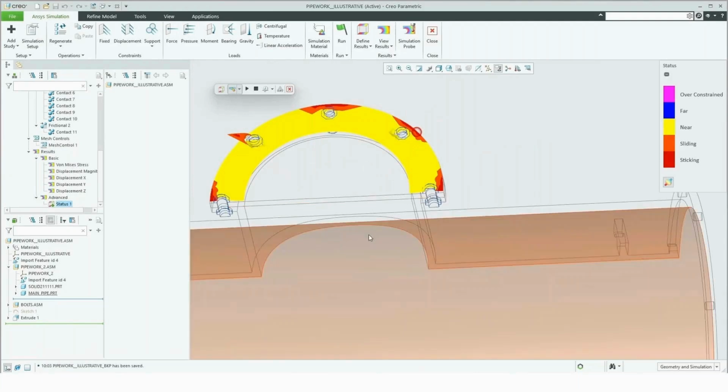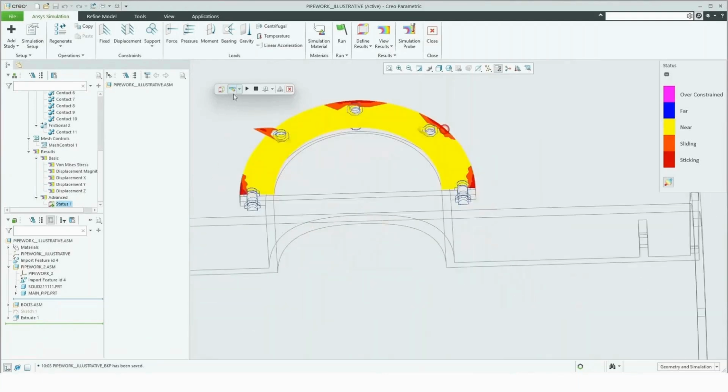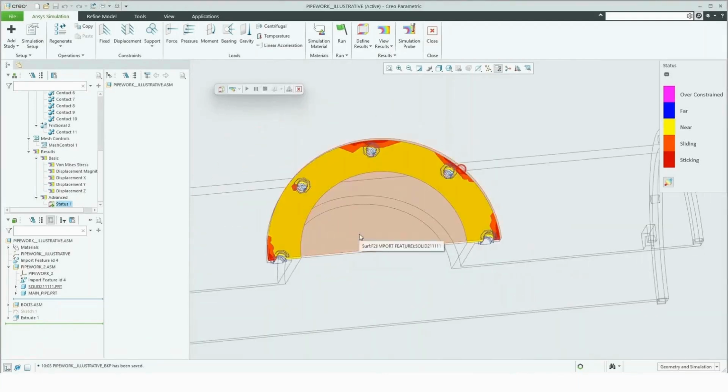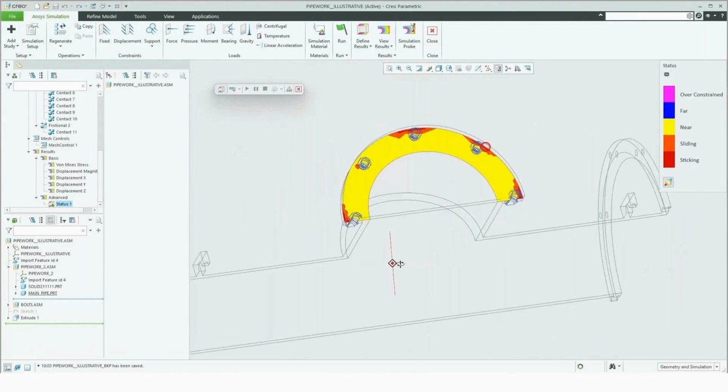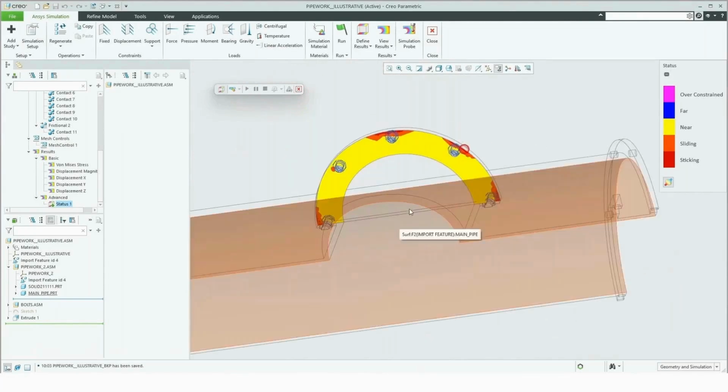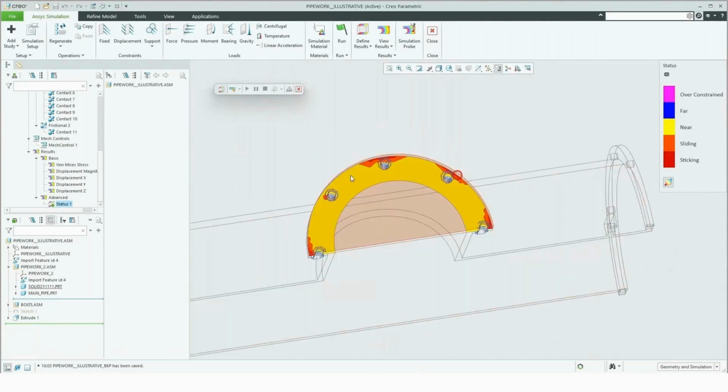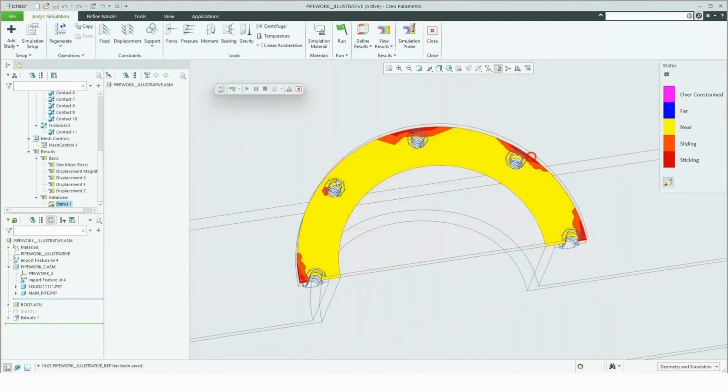And we can see now that if I remove the deform shape, we're now getting less even contact, as we would expect, because we would expect to see some separation. But we've got some kind of slightly uneven contact around the bolts. This might be an indication that maybe we'd want to look at refining the mesh in this area.